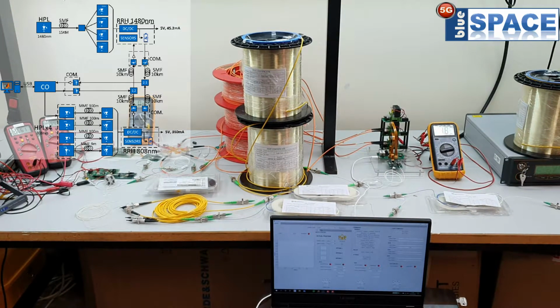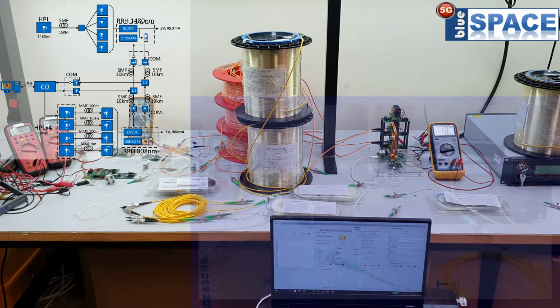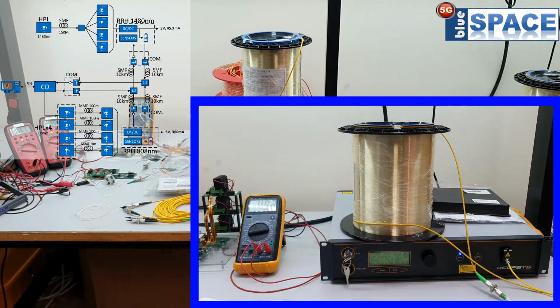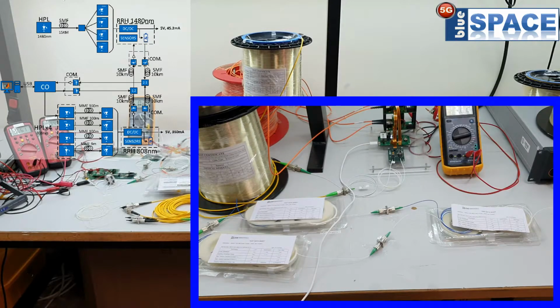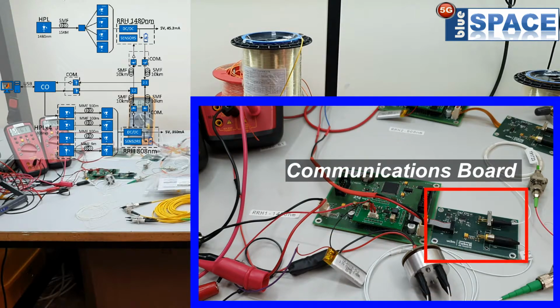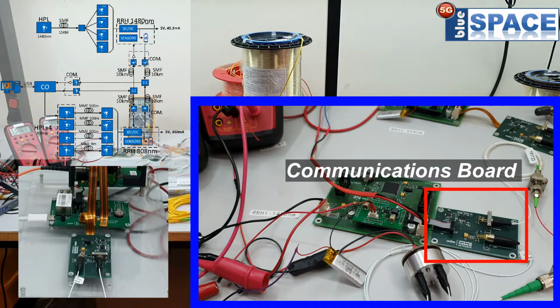In the 1480 nanometer system, a 1480 nanometer high power laser, a 15 km optical fiber, a 1-to-4 optical splitter, and a 4-cell array to feed the first RRH. This RRH communicates with the central office using two 10 km single mode fibers and a communications board, which also appears at the central office.